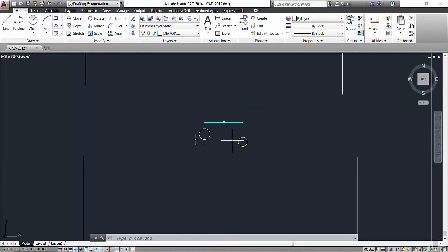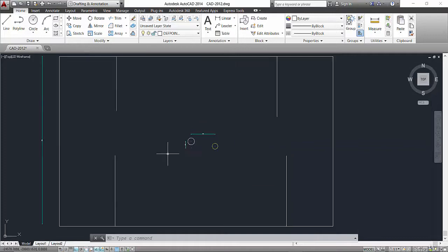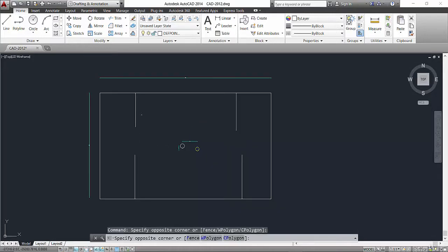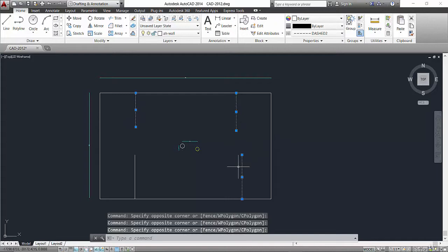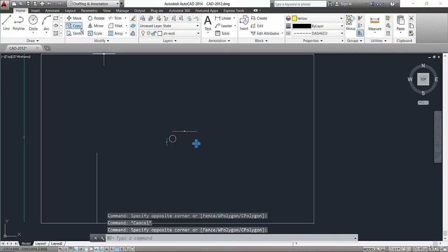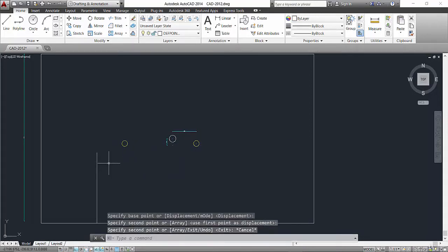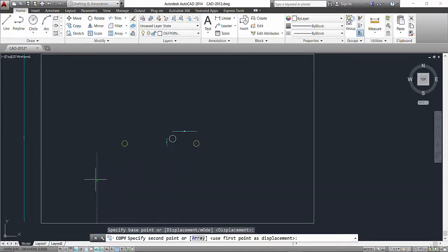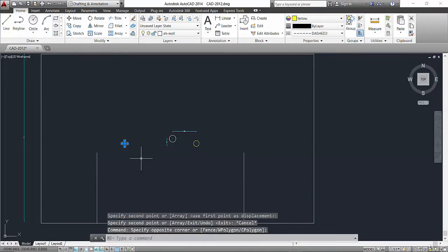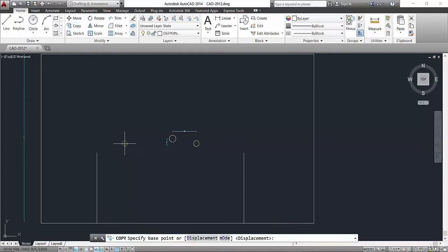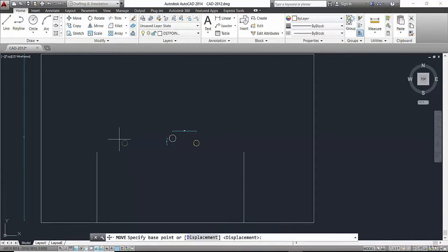The center of rigidity represents the rigidity of the shear wall or the system used for resisting the earthquake. That means if we have a shear wall here, the center of rigidity will be in this place, near the shear wall. If we have a shear wall here, the center of rigidity will move right.